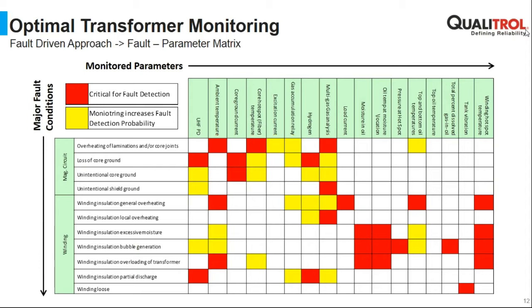And that's, as we have seen before, it depends on the history, so to say, of the fleet. It depends on different parameters, for example, how a transformer is operated, overload, not overload, and if I have a transformer maybe close to a capacitor bank, where it sees very often transients, and so on. And these are the main things.